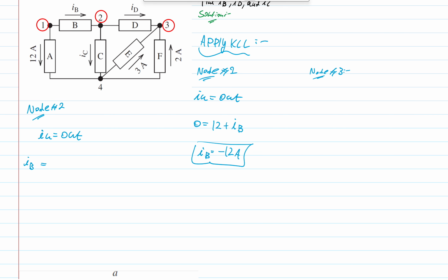So that's going to become 4 and the R, which is how much? 2, which is going to give us the value of 8 volts. For V2, I is basically 4 amperes. Got R, which is how much? It's 3, and that's going to give us the value of 12 volts. Like that, you're done.